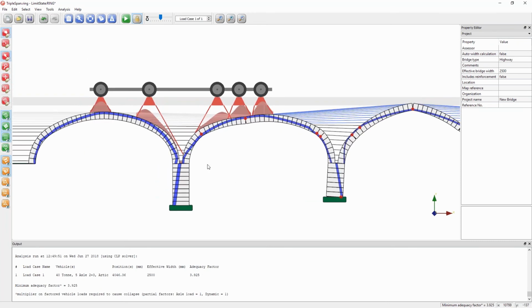I've actually specified backing material above each of the piers, and that is effectively there to represent relatively strong masonry material of the sort that you would typically see in a structure like this. So typically, for this kind of geometry, you would have solid material above the pier head, whether that be concrete or masonry material.